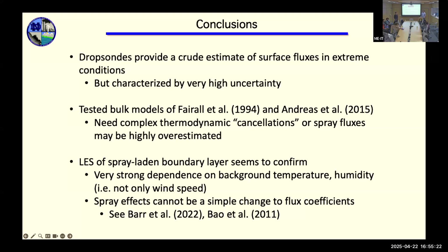But these are sub-Kolmogorov droplet sizes? Yes, the Kolmogorov scale might be 100 micron in these kinds of situations. The dissipation rates are so high that in the atmospheric models, in the temperature equation, you actually have to retain the viscous heating term. So it's close, I would say. What's your Reynolds number, do you think? I don't actually know. Sometimes I get mixed up as to what height scale you want to use, but it's something like this.